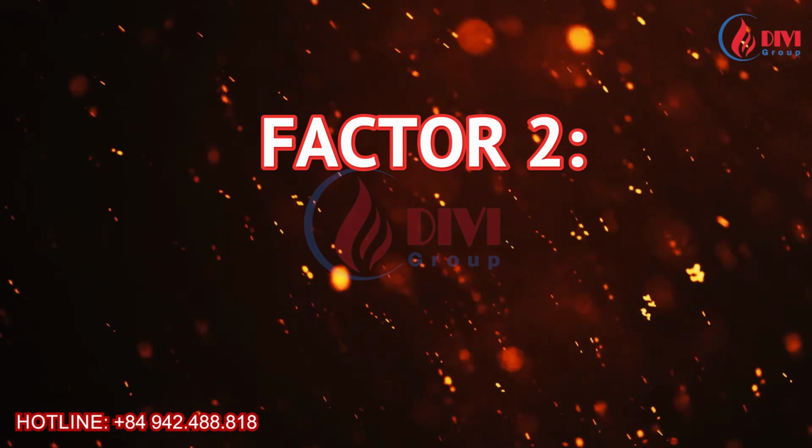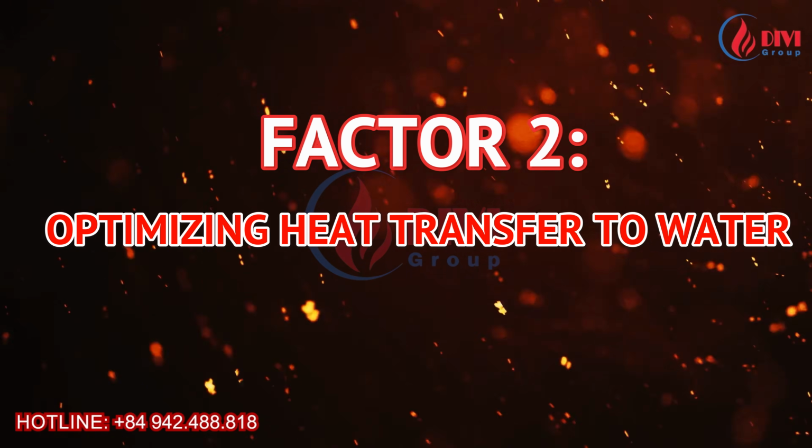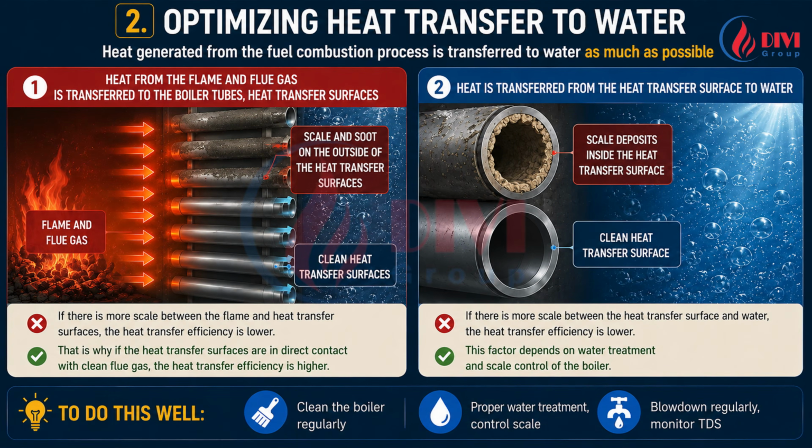Factor 2, optimizing heat transfer to water. This means maximizing the amount of heat transferred from combustion to the water. Heat transfer efficiency depends on 2 fundamental factors. First, heat from the flame and flue gas must be transferred to the boiler tubes and heat transfer surfaces. The fewer deposits between the hot gases and these surfaces, the better the heat transfer performance. Cleaner surfaces result in higher efficiency.